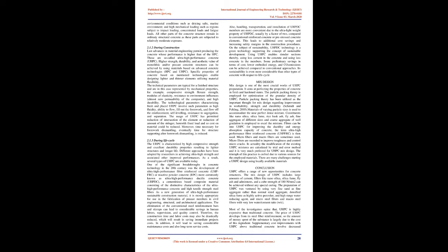One of the significant breakthroughs in concrete technology in the 20th century was the development of ultra-high performance fiber reinforced concrete, UHPFRC, or reactive-powder concrete, RPC, more commonly known as ultra-high performance ductile concrete, UHPC, a cementitious-based composite material consisting of the distinctive characteristics of the ultra-high performance concrete and high tensile strength steel fibers as a new generation of ultra-high performance sustainable construction material. It is mostly appropriate for use in the fabrication of precast members in civil engineering, structural, and architectural applications.